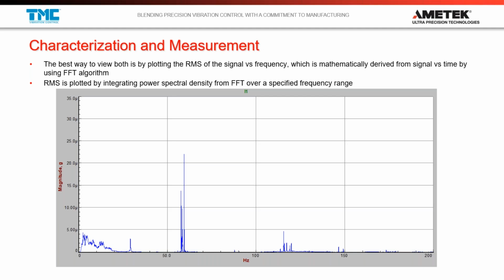then we look at the low frequency, and our fast Fourier transform has given us a little bit of information telling us, well, hey, there's a whole lot more noise going on at the low frequency. And we got to start thinking about those low frequencies, because those sources are going to be things like building sway, and those are going to be the real building vibration, that floor bouncing up and down at low frequencies that you really got to start thinking about when you're thinking about the instruments that you're using on this floor.